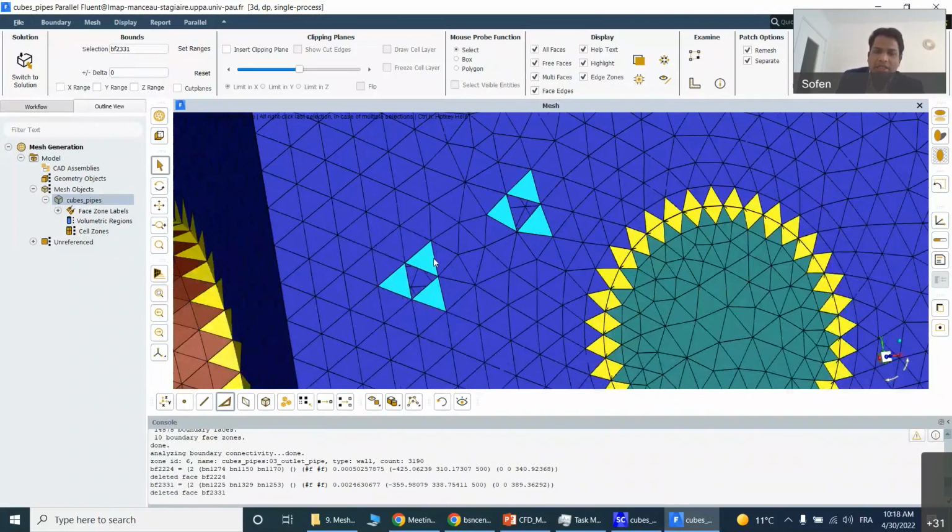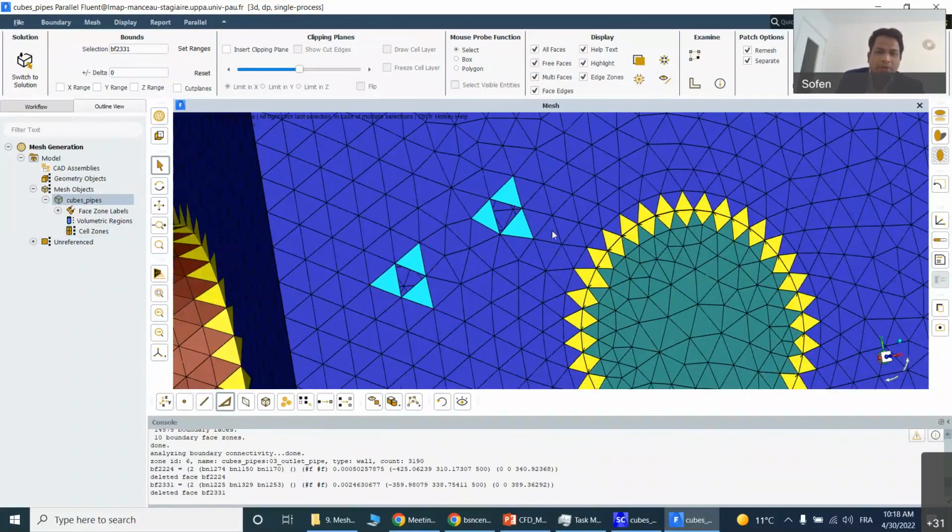This is what a free face means. Since I deleted it here, I know a face is missing. If I have not deleted it, then by default the geometry has some problem and a face error comes during the face meshing, and some elements are not created. That time it is possible that it will show you the free face.